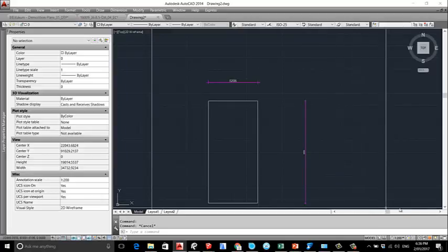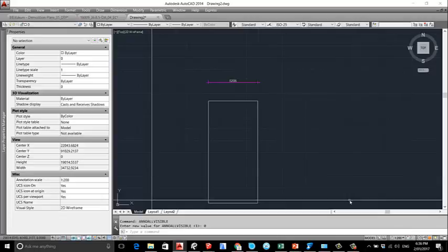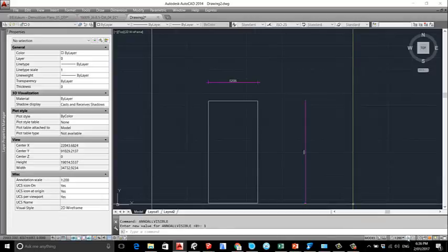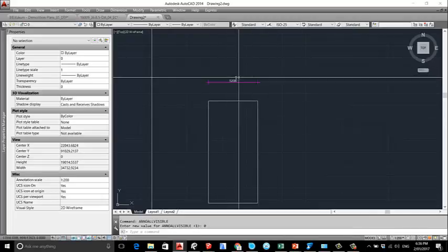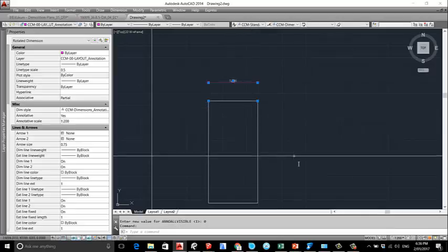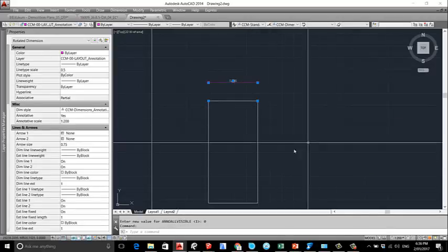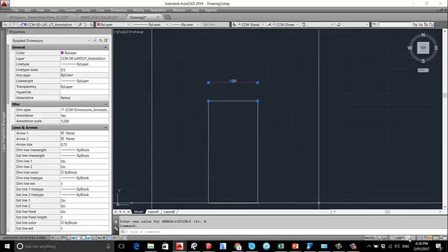Also, we can say that things don't display if they are not in the proper scale, which is this icon here. See? We turn it off. If we are in 200 now, which is the drawing is in 200, this is set up to be 200. That thing wasn't set to be 200, and we click in here, so it's hiding. Annotation visibility: show annotative objects for current scale only.